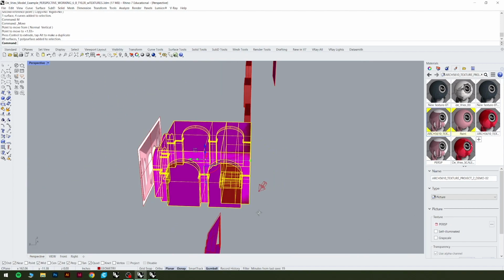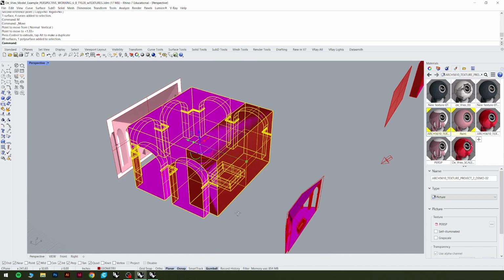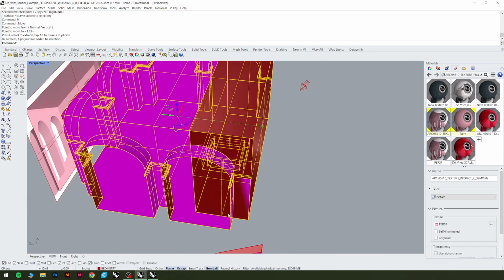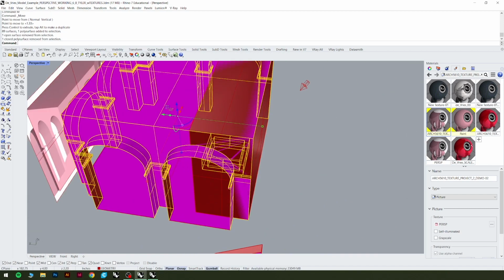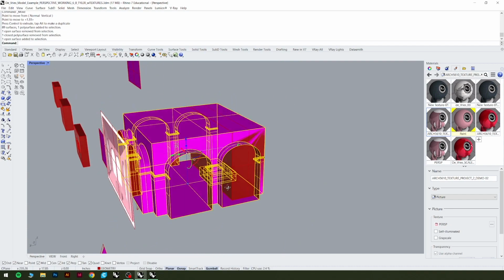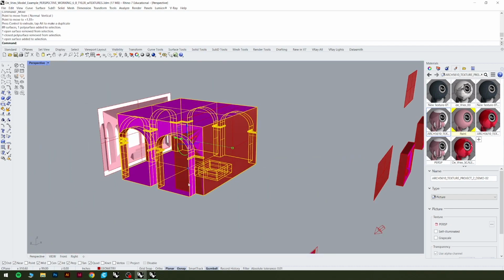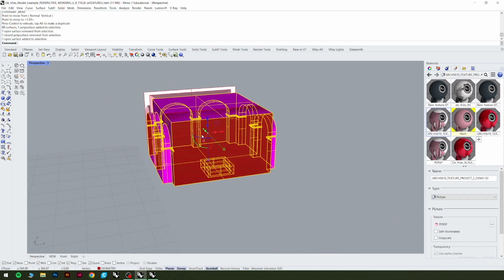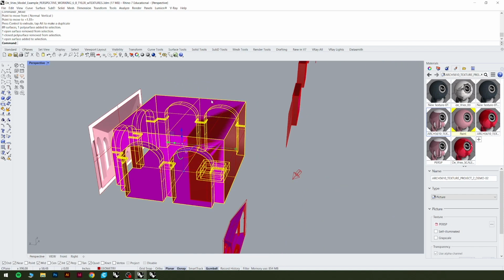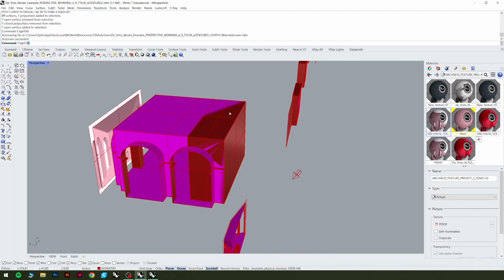Okay, so now you want to select your object. You do not need to select, and actually you don't want to select that bounding box. So just make sure you're not selecting the bounding box itself, but you will need that bounding box. It should be the size of the inner room, and it should be 4 inches deep. And now you'll do the cage edit command.